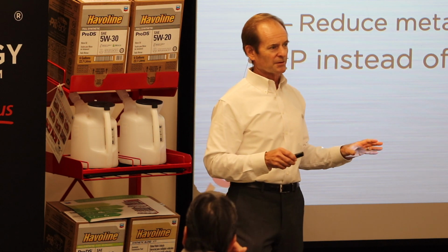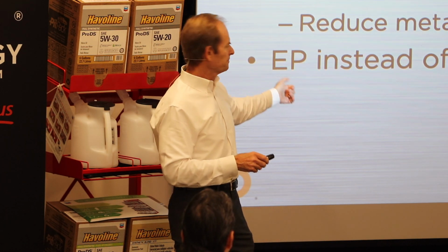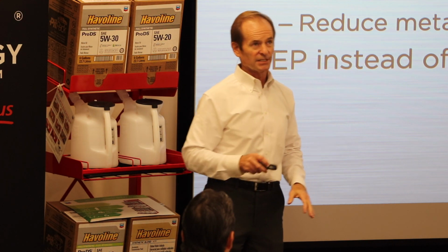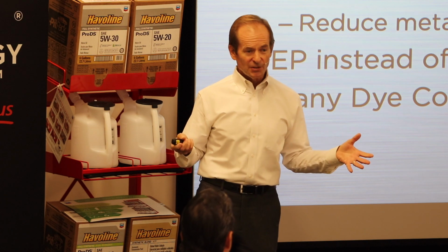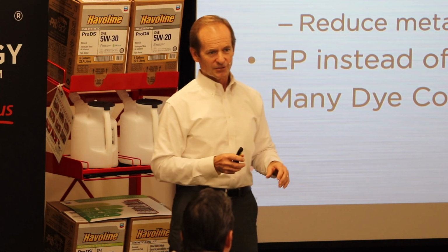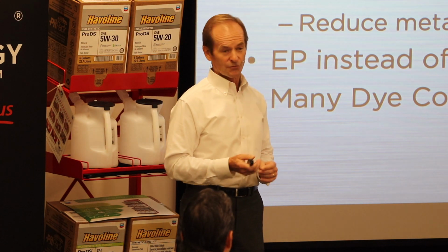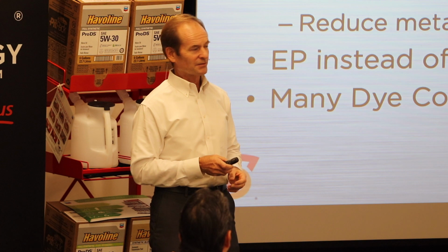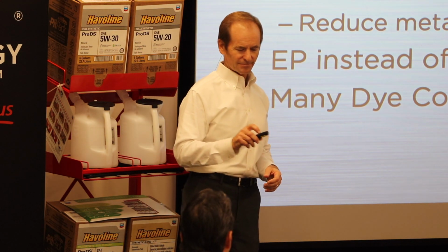There's definitely different aggressiveness in how well it protects metal from wear. Very important in CVTs. Okay? And in addition, at least the CVT people had the foresight to not dye it red. You'll see it dyed colors, but all the ones I've seen, at least they weren't red, so you don't have a chance to confuse that with your red transmission fluid.